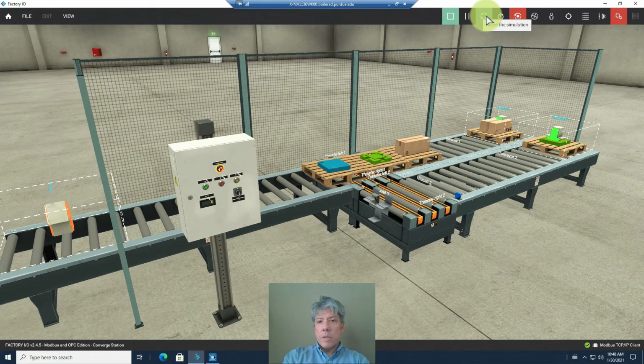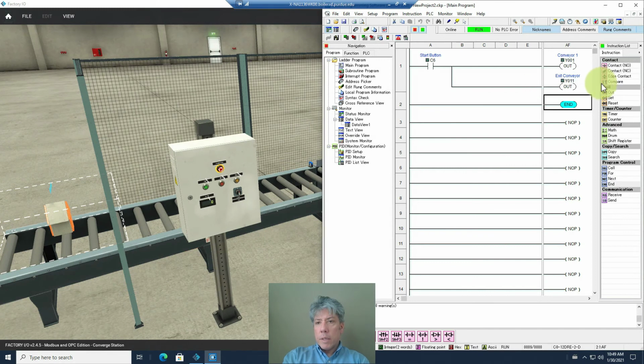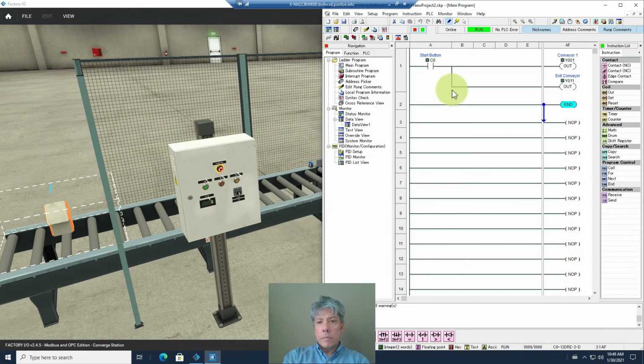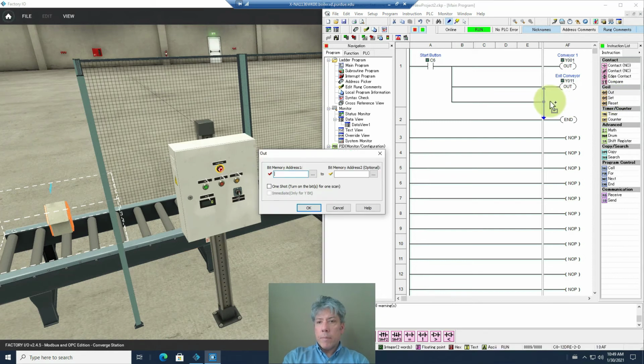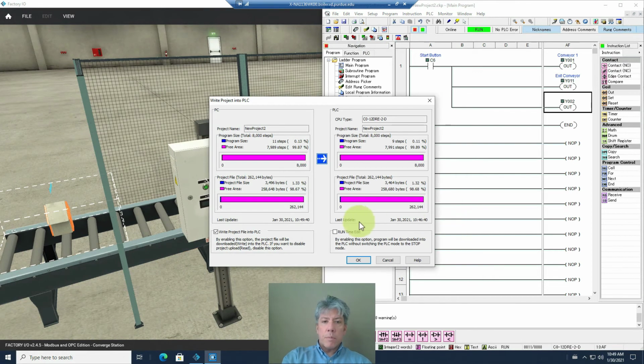So let's reset our simulation. And let's go to Click Programming Software and let's add another branch. Bring it over here and connect an output. And remember that the load 1 was immediately after the conveyor 1 address, so it must be Y002. You can verify that with the Modbus address. So now let's upload this to the PLC and see if this makes things work a little smoother.